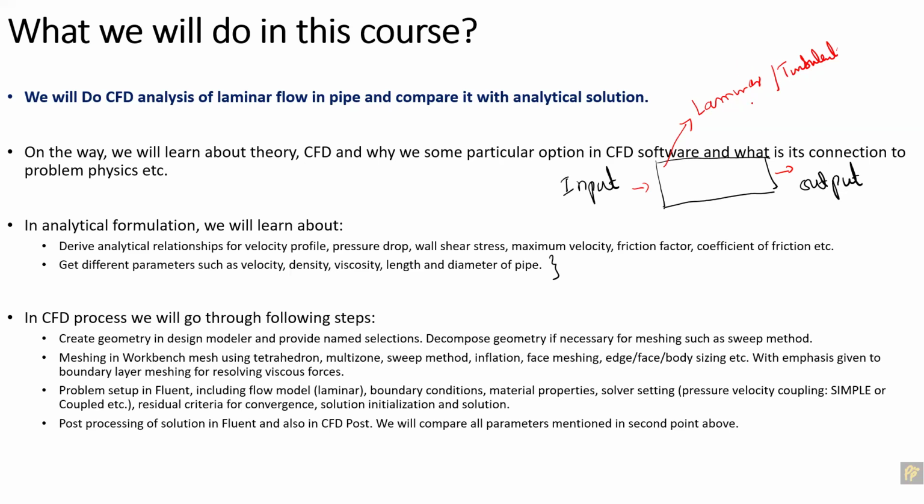So you have to turn on that particular model in the CFD software. And for example, if you are running a turbomachinery simulation like a wind turbine, you must know whether the steady state solution would be enough or a transient simulation should be used.